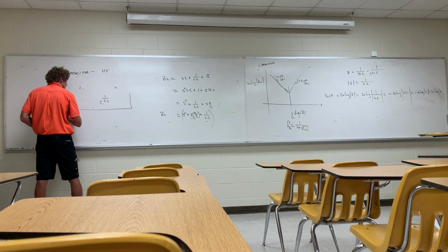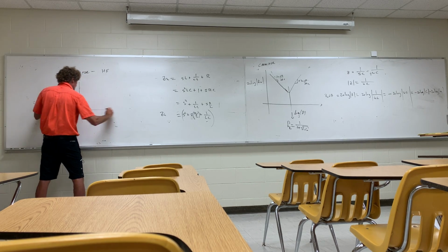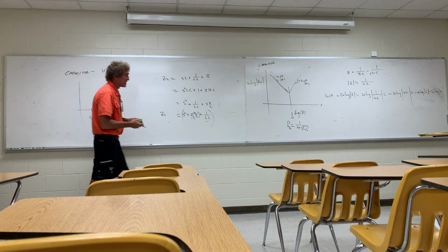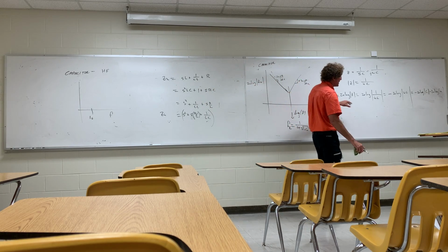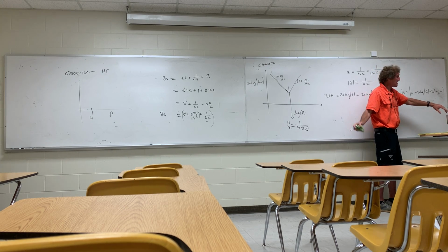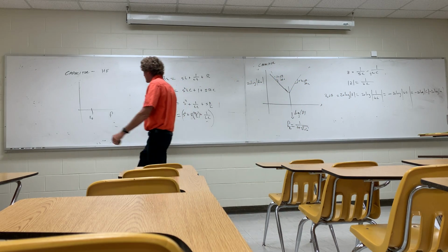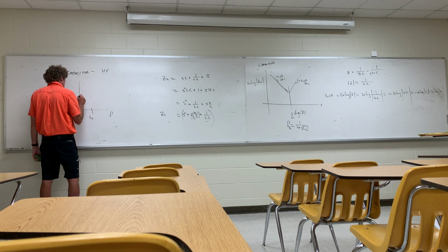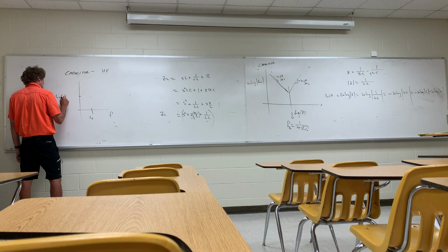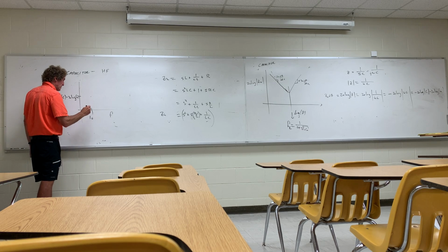Now, if you just plot versus frequency, let's say I'm here at, just call it 10, and I look at this plot. I know I have minus 20 times the log of C. That's a constant, right? It never changes, correct, class? This is minus 20 times the log of omega. So if I'm at this point, I'm going to have a certain value. It's going to be minus 20 times log of C minus 20 times log of omega at that point.